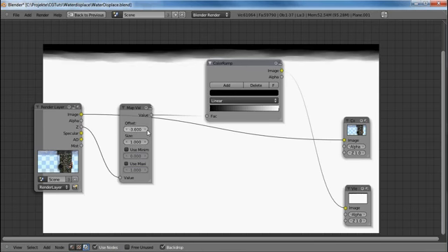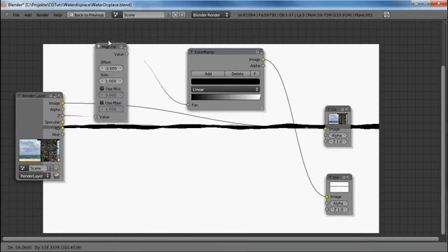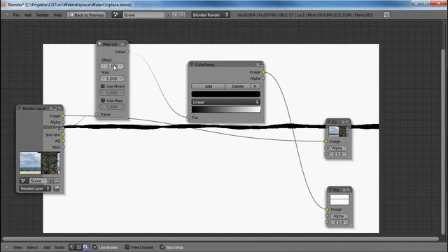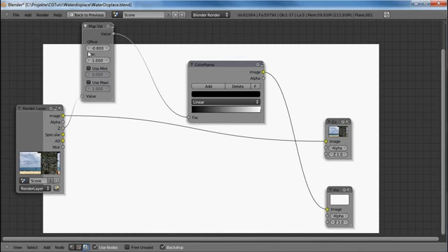That's a lot more than I thought. Actually, this is not the best image to use. Let me render another one. Okay, with this one, you can actually see the bottom of my background picture in the background, but that doesn't matter at all, because all we're interested in is a depth map. So let's try changing this to minus 0.8, and that's still not enough, so let's offset it a little more.